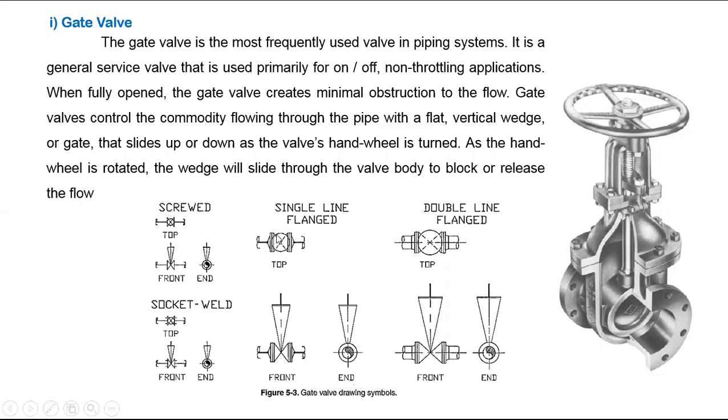If you don't have time and you want to commit immediately, you have to show single line. But you have to provide space for the adjacent pipe correctly. Single line means just to show, but you don't simply draw the single line. You have to see the spatial requirement. If you are drawing some 200 mm pipe near the wall, you have to calculate the pipe OD, then provide space for the flanges and clearance for the bolting. Everything you have to think in mind, then only put the center of the pipe.